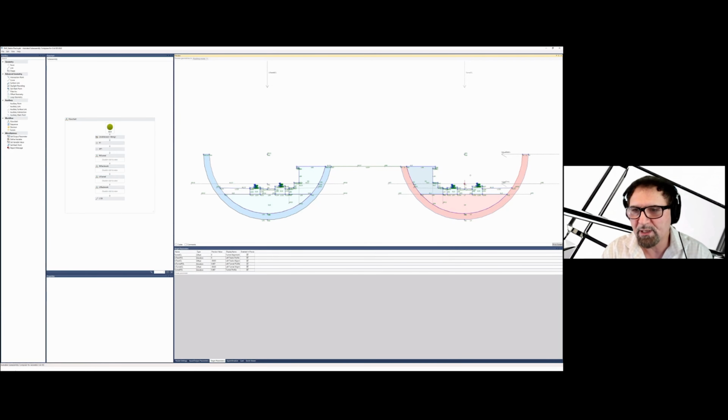This will later on be taken advantage of when synchronizing the model with the Revit. I'm going to use the alignment details that are passed straight through that marker point there, or a reference point, and there will be a straight line that will be then used as a reference. So in Revit, that reference line will be used as a host, and we will host pretty much everything that goes into the station